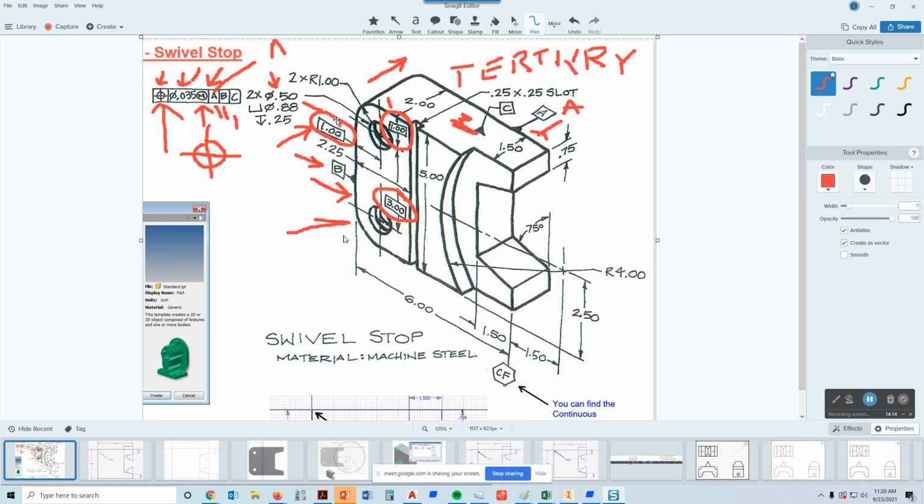So we have regular dimensions that we call the nominal size because we can have a plus or minus tolerance on them. We have reference dimensions, which are in parentheses, and reference dimensions are just included as a reference. Then we have basic dimensions that are part of geometric dimensioning and tolerancing, and these are theoretically perfectly located datums or features that we can dimension to, okay?